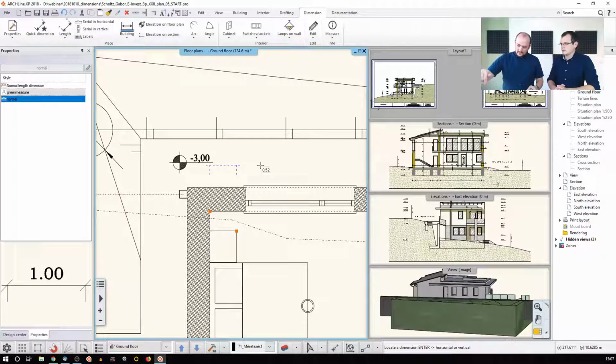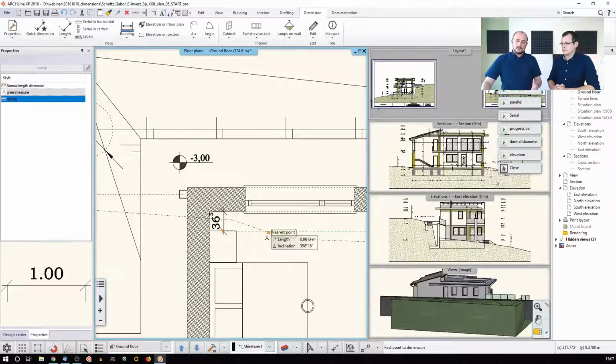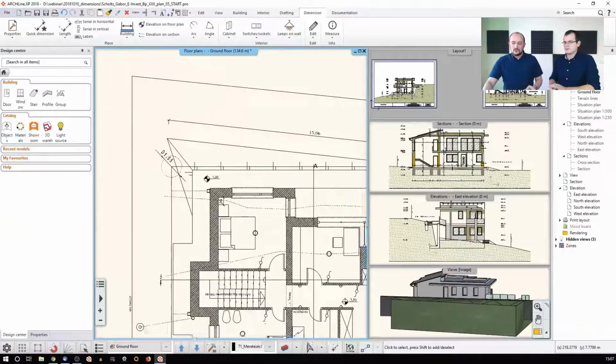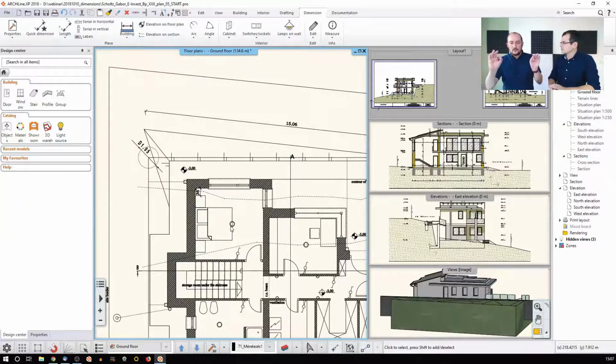If I right click again, it will switch to the vertical component, and then I just click here and the software places that measurement. So whichever component I like, I just move it someplace, click, and then I just continue adding more and more dimensions. This is the simplest and most primitive tool to use if you would like to pick up 2 random points and then just measure their distances anywhere in your drawing.